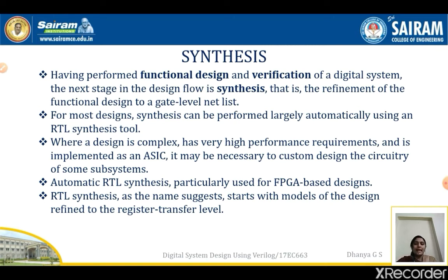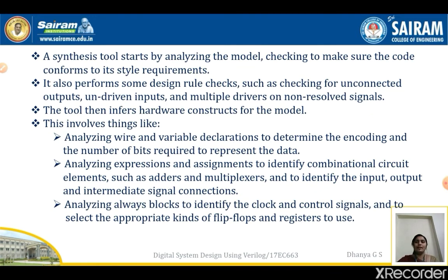RTL synthesis, as the name suggests, starts with models of the design refined to the register transfer level. A synthesis tool starts by analyzing the model, checking to make sure the code conforms to its style requirements. It also performs some DRC, which is design rule check, such as checking for unconnected outputs, undriven inputs, and multiple drivers on non-resolved signals. All those things will be checked when you are analyzing for synthesis.